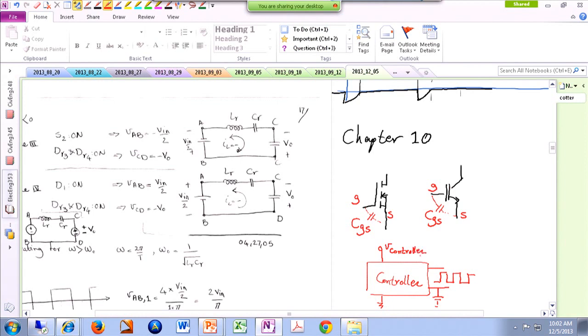One solution would be directly connecting this to your switch, assuming that you have a switch that has a source-grounded topology, like a boost topology. Remember, in the boost topology, the source is grounded, so no problem.